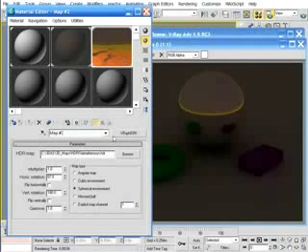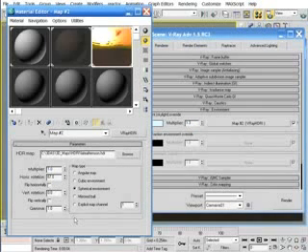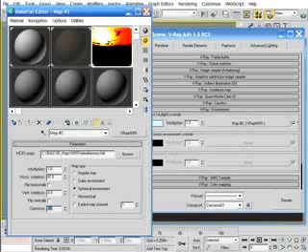There are two additional controls in the HDRI map that are quite important. First, the multiplier is pretty straightforward and nothing new. Doubling this simply doubles the amount of illumination the HDRI wants to radiate. Remember that when a map is loaded in the environment channel, this multiplier cannot affect the illumination in your scene at all. The multiplier in the material editor would be where this control lies. Also, you can see that we have a gamma setting here, which you might find useful to play around with because you can use it to create some quick adjustments to the illumination in your scene and create some pretty nice moods, such as adding a more nighttime appearance to the HDRI that you're using.